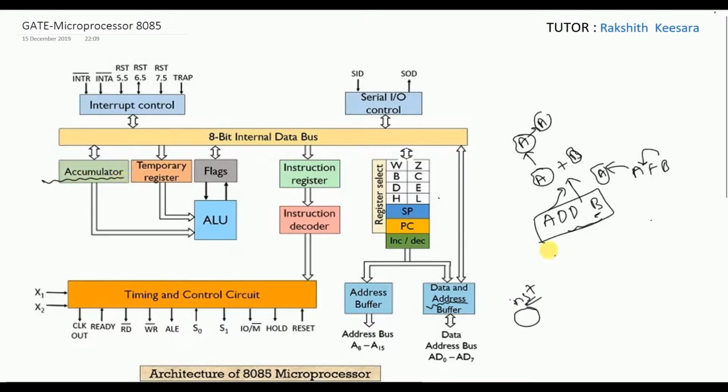So for any operation, either subtraction or addition, we need two registers, guys. Say if you want to add two numbers, you need two registers. In that, one will be the accumulator. This is fixed. Why is it fixed? Intel manufactured it like that. So for any operation, one register is the accumulator. That is fixed. The second register is our wish: ADD B, ADD C, ADD D. That is our wish.